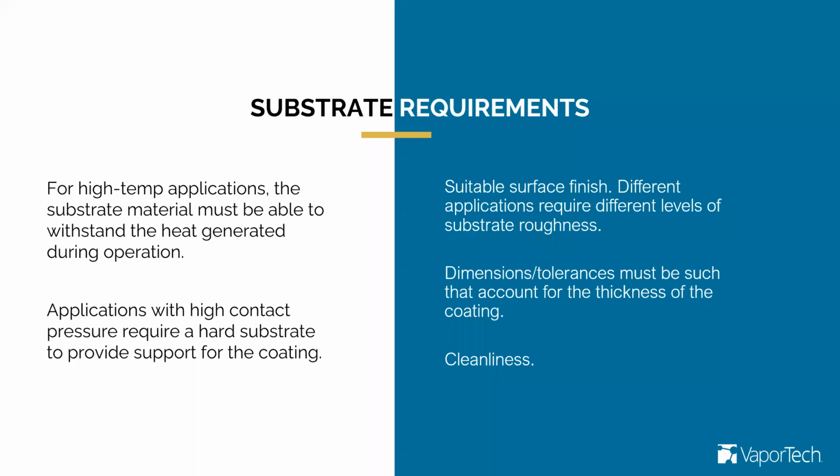For instance, if you have a tool that's going to operate over 600 or 700 degrees C, you cannot use a tool steel. You would have to go to a carbide tool, for instance, right? So that has to be kept in mind.